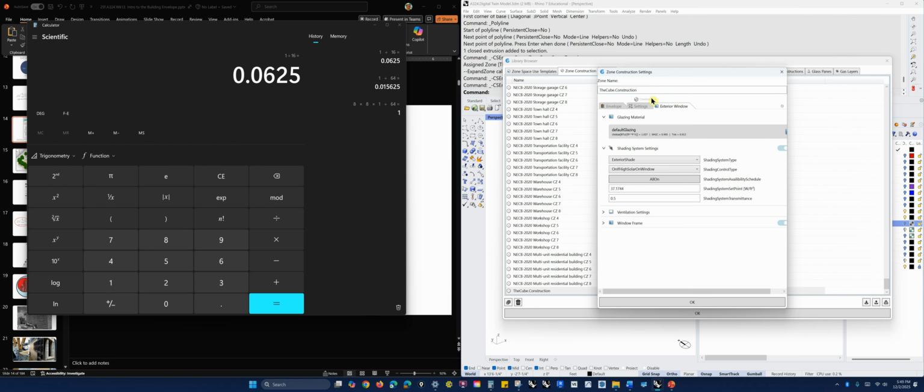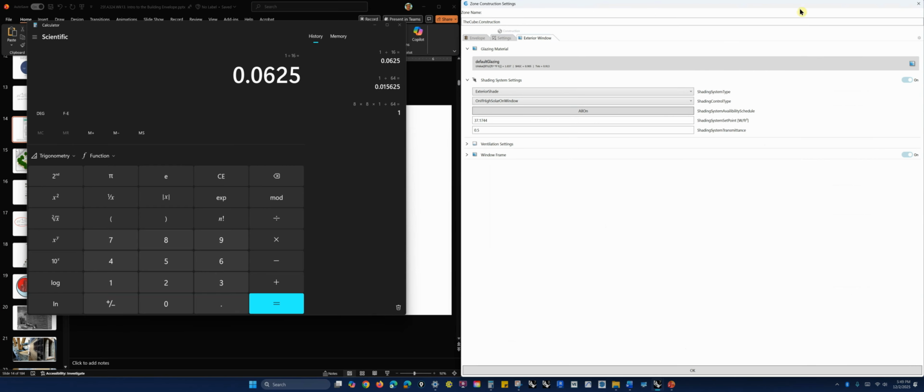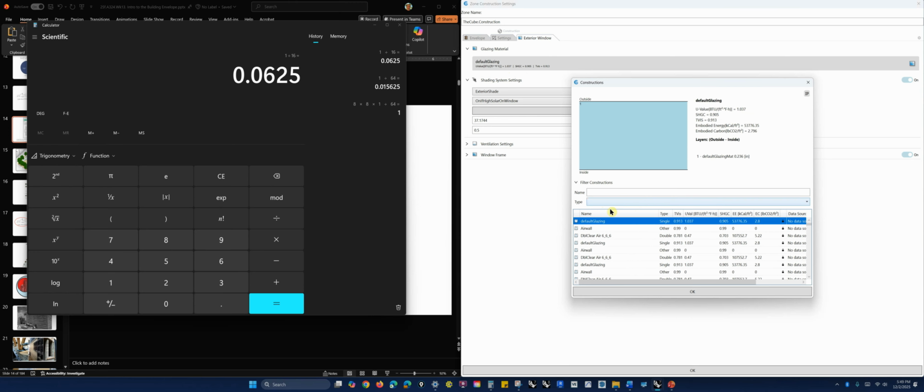The exterior window: since we have chosen the window to wall ratio option, we can select our exterior windows in this dialog. Later you'll see that I'm going to actually add windows if I get that far in this video, and then you'd have to do this workflow someplace else, but it's the same exact thing. I'm going to start with default glazing. That's actually pretty close to what you have if you're using the plexiglass like I purchased. We have a solar heat gain coefficient of 0.9, a U value of 1, which is an R value of 1. Pretty bad, but still something.